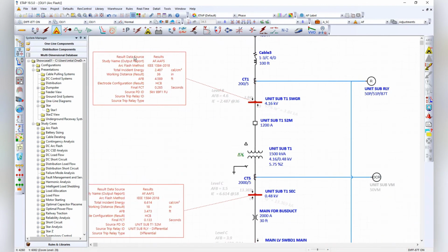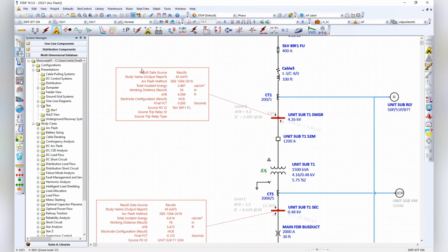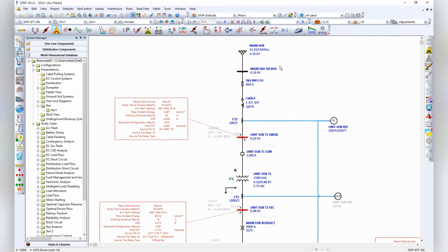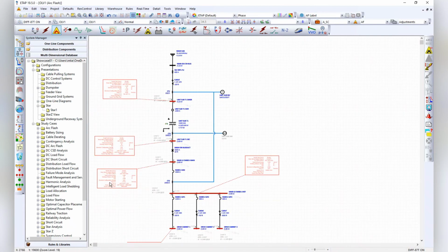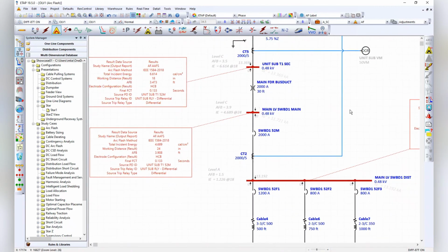And we haven't touched on this, but you can always see that the primary termination on the primary breaker coming from the substation will never change. Whatever I do downstream, down here by the unit substation, those numbers are always going to be determined by whatever it is on the substation fuse, or if you have any other feeder breaker with another protective relay and protection up here, that's what's going to determine that arc flash number. So that is the differential alternative.